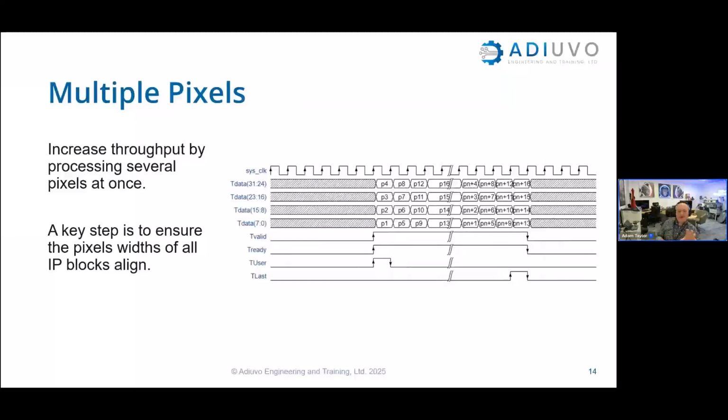is that if we're going to have an image processing chain, we should try to use as many IP blocks from the library as possible. And we need to make sure that all of those IP blocks support the pixels per clock that you expect. Some might only support 4 or 8 or 2. So you have to make sure that the entire processing chain, up until you do something, i.e. put it in DMA or take it out of DMA, is able to support that.